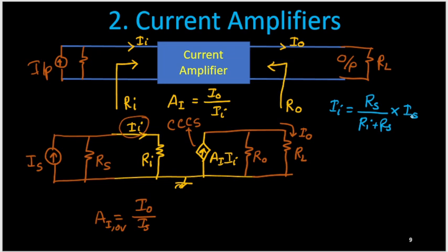We have discussed that in detail in my previous videos in the circuit theory lectures, so if you have confusion, please go through that. It's a current divider. The current through this branch will be the opposite resistance Rs upon the total resistance Rs plus Ri, times the supply current Is.